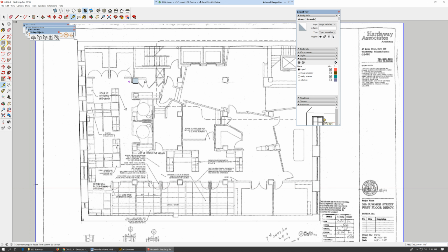We're just roughly prototyping in plan what we're looking at for space here. So I'm going to copy this every 17 feet in this direction. Tap the control key. 17 feet. 2, 3, 4x.